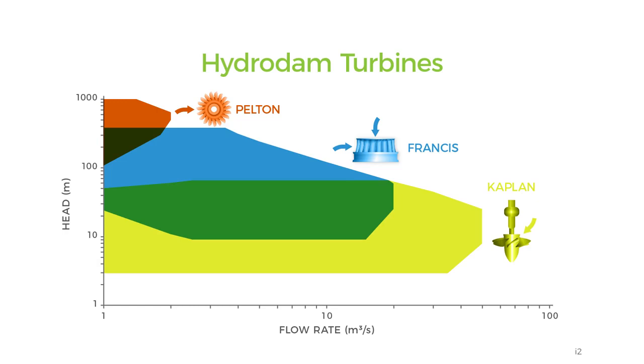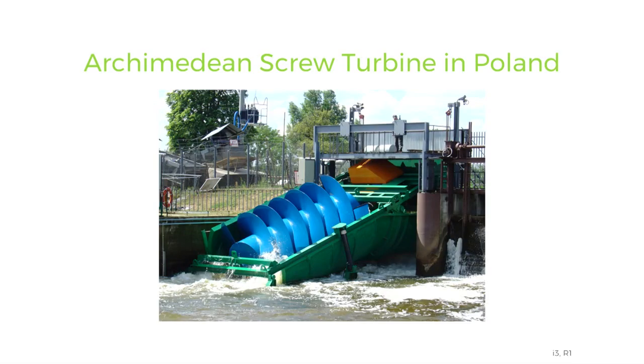It is the most common type of water turbine used today. It looks a little bit like a rotor on a jet engine and uses principles of both the Pelton and Kaplan designs. But these conventional turbines cannot extract the energy from low head resources efficiently. We will need different designs to efficiently extract energy from very low head resources.